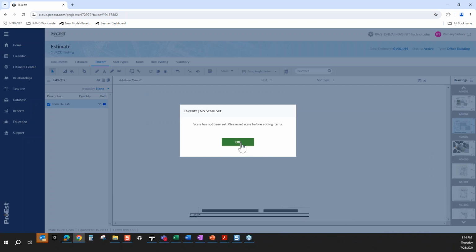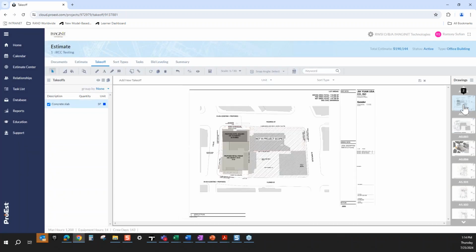So let's go back to our sheet. And to perform the takeoff, we'll just hit the measurements tool here. Yep. And then I'll have these crosshairs here, and I can select the slab I'm trying to do a takeoff on. So maybe this one is a good one to start off with. Let's go ahead and do that.